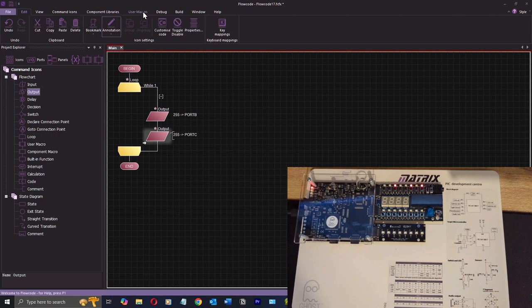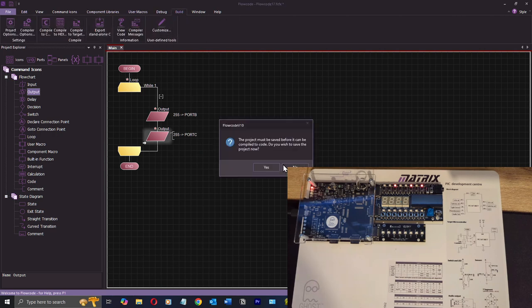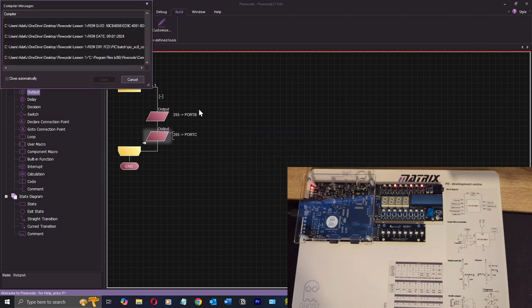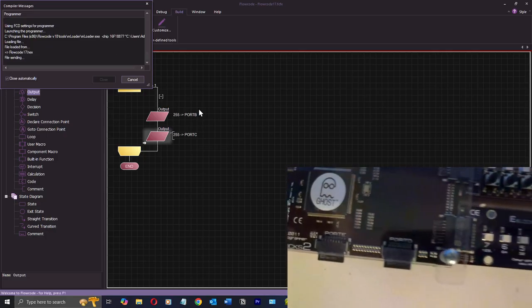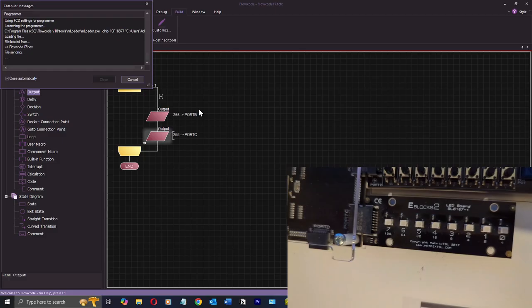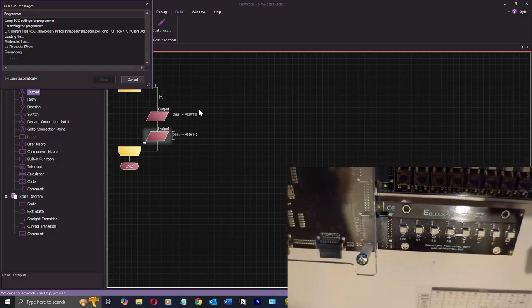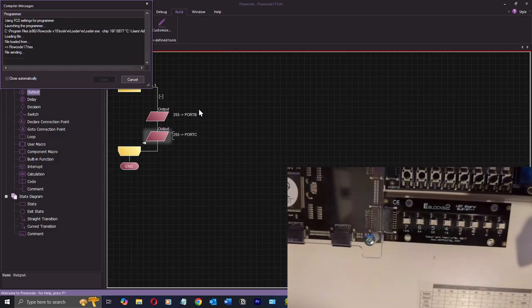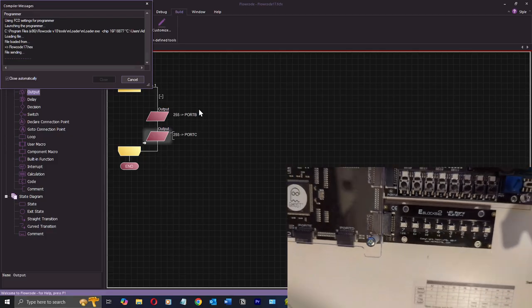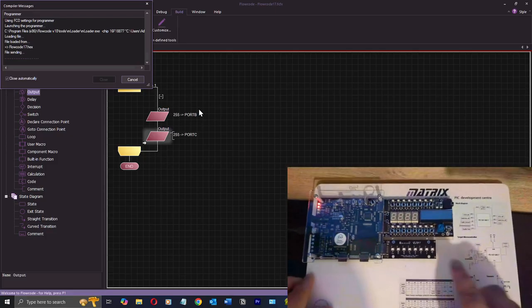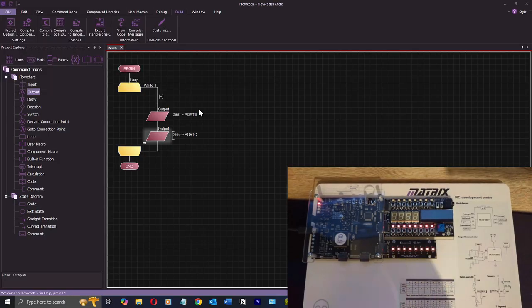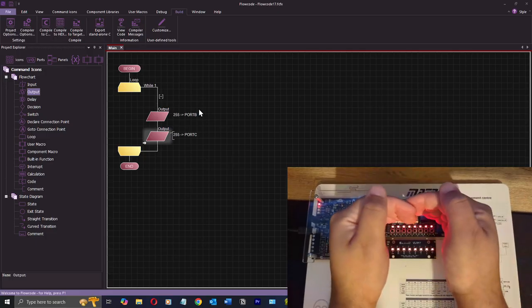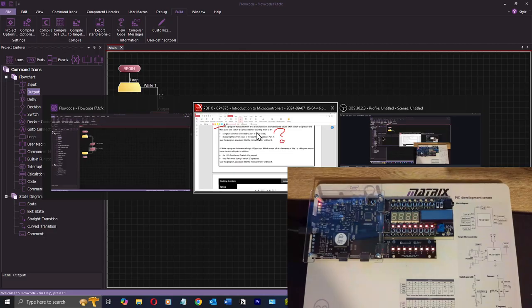Let's just compile this. So this is an additional board, a little E-blocks add-on board, but they're never as simple as they seem. To me, that's just 8 LEDs there, so I should just be able to write the same byte that I'm writing to here, 255 in this case, to there. Okay, yeah, so it turned on. All right, that's fine. So we've turned on all these LEDs.